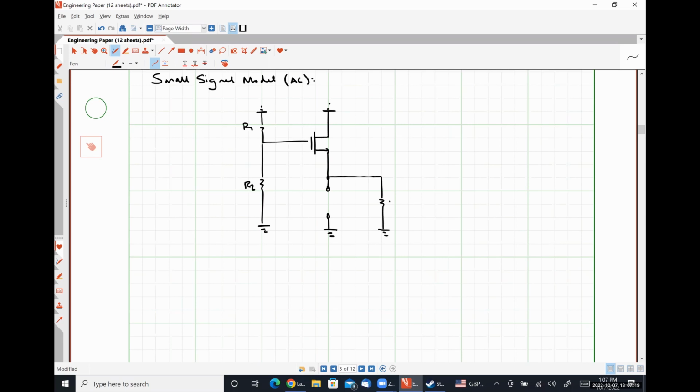Here we have our load resistor RL. Here's where our output voltage is taken. Over here on this side, here's our signal resistance. Oh, and I forgot to draw my input voltage, so let's put that in there, Vin as a function of time. So this is our starting point for drawing our small signal model.